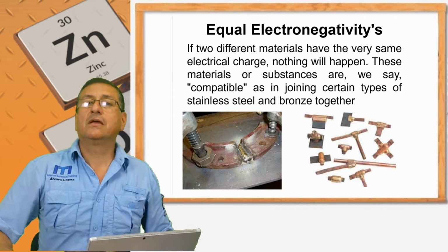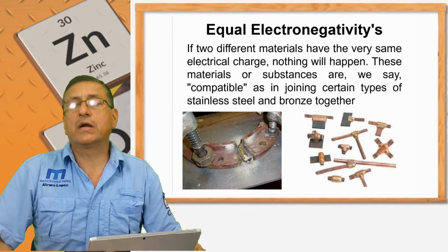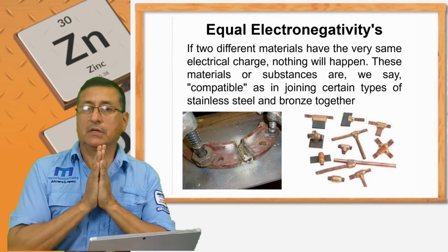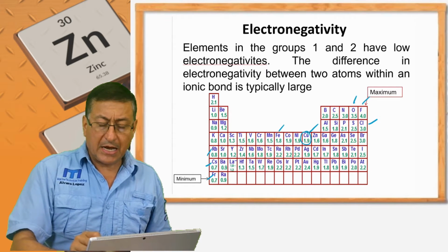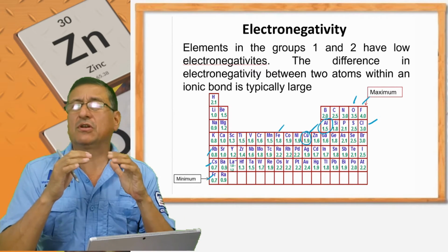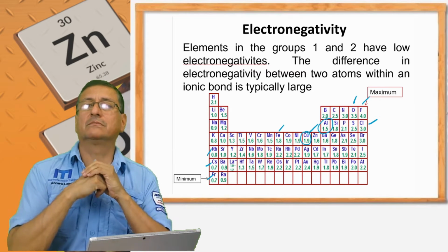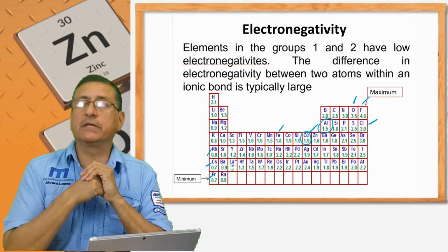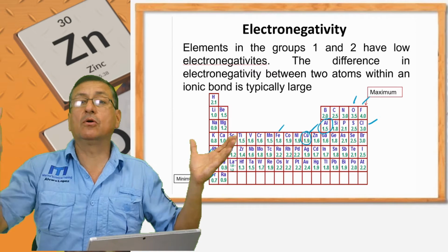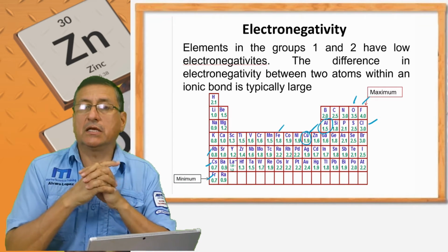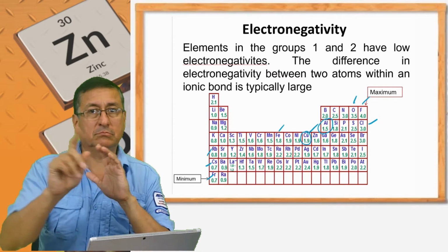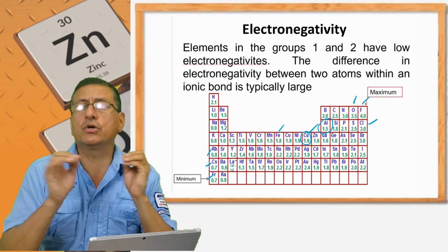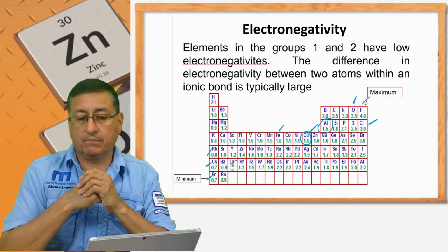In the opposite way, when you have different levels of energy is where one metal corrodes the other one faster. And the best example in marine application is copper and aluminum. If you check the periodic table, copper is 1.9 and aluminum is 1.5. It's a big difference. For that reason, copper and aluminum, and additionally the structures are completely different, are not good in marine environments. You need to be careful when you have a boat with an aluminum hull with the hardware used in that boat. Of course, the through-hulls in bronze, no, because the boat is aluminum. Probably you need through-hulls in stainless steel, marine grade. Stainless steel is a good choice for through-hulls and hardware for aluminum boats.